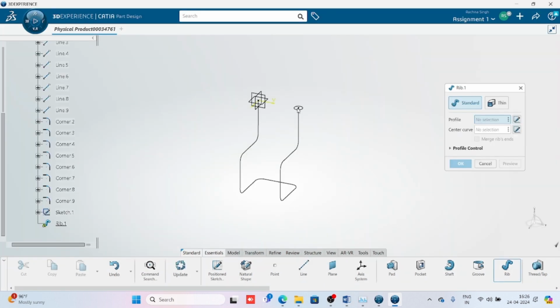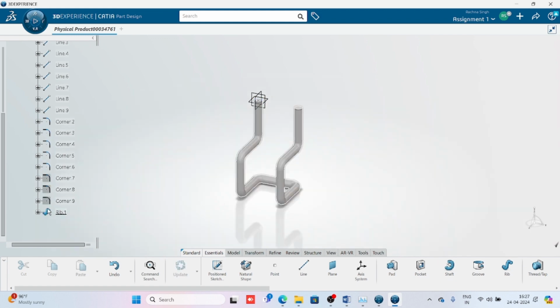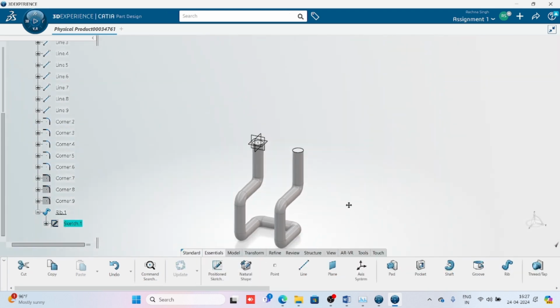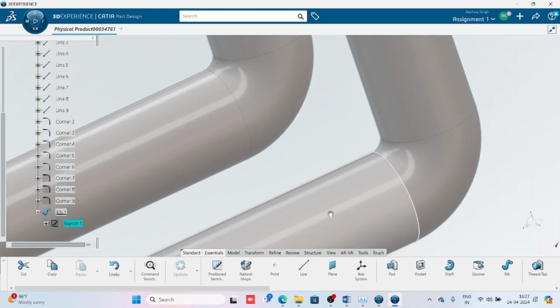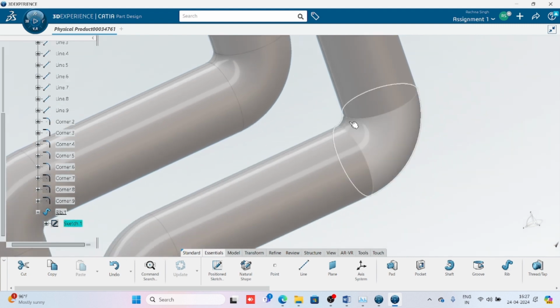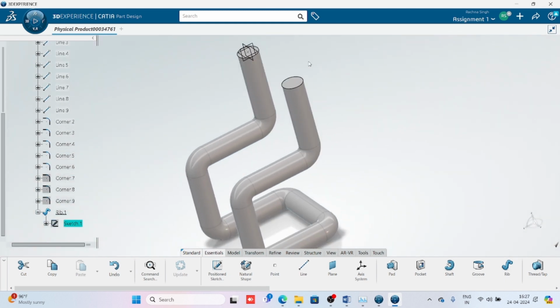Now if we want to create a profile with more thickness, like I am just going to change this thickness to 25. Now you can see this is the bending radius. On 25 it is bending, but the bend is very small. You can see the bending radius inside the profile. Now if I increase the diameter from 25 to 30, the profile will not get created. But my requirement is I have to create a profile with 30 dia.